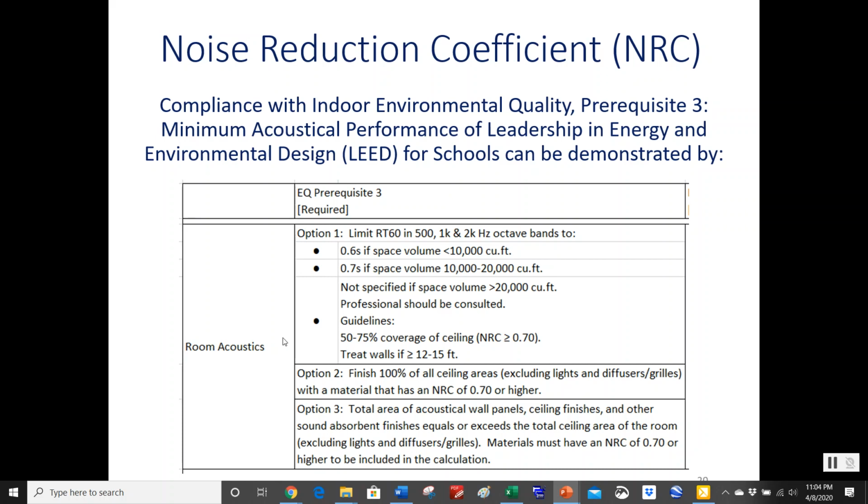For room acoustics, you can do calculations to meet a certain reverberation time based on the volume. And it's a little bit questionable. Does this actually, by the strictest definitions, even apply to a space like this, a classroom space? Because it's a small space. It doesn't meet all those things like having mostly reflective surfaces, having highly diffusive surfaces, having all the surfaces being roughly the same. So it's not a diffuse sound field. So it's kind of hard to really apply a reverberation time to it, but it's still done.